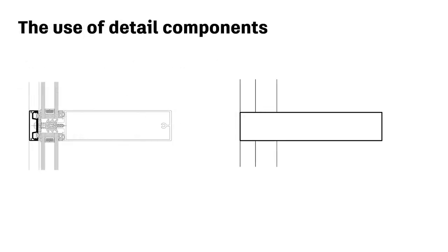Many elements within your Revit model will be created with a specific level of detail. For example, an aluminium window frame would be modelled with simplified geometry to improve the performance and also aid the production of views at differing scales. However, detailed drawings and sections at higher scales would need to convey more detailed information as shown in the image